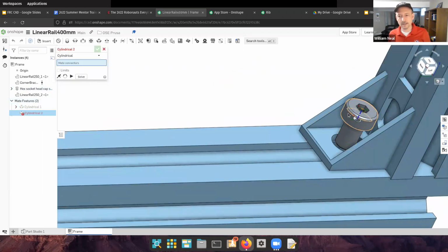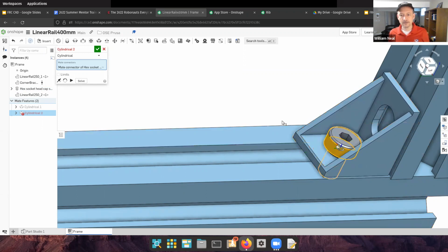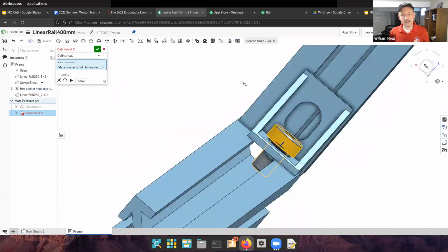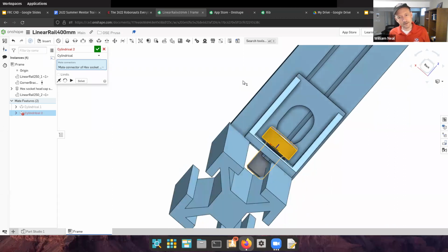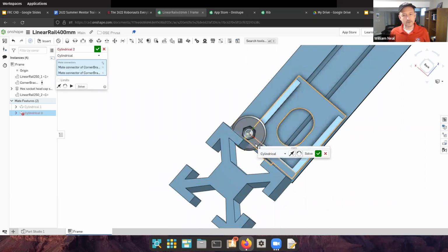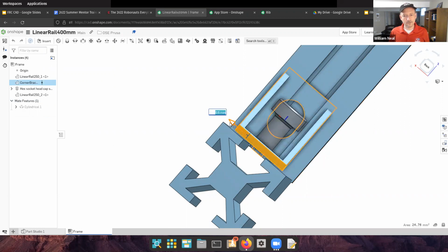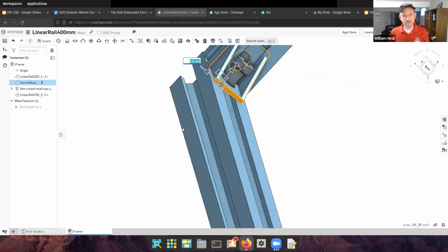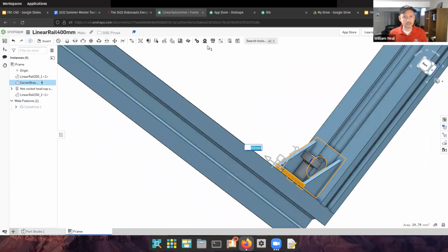Now that's good. And this one, I should be able to click on this. I wonder if I can move it around now. There we are, I just fastened the screw down in there. And this is actually not quite the right length, but it's close. So I can see that my 8mm screw is close. This whole part here does have to move though. Whoa, I was not done with that. And so there we are. I should still be able to move this over a little there, and I can center it. I can do all kinds of things and line up everything. So that's what I will do with this assembly set of tools here.